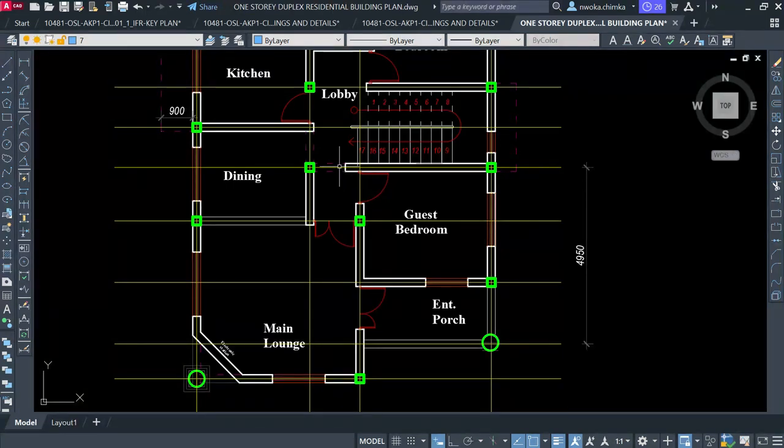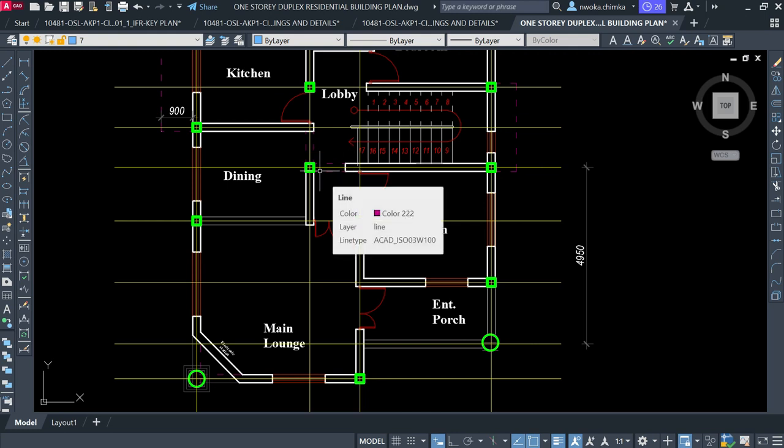That's because you have done it over the years, and you have seen that any column distance below 6 meters should be able to give you at least maximum 4y16 bottom, and let me say 3y16 top. That should be the maximum.